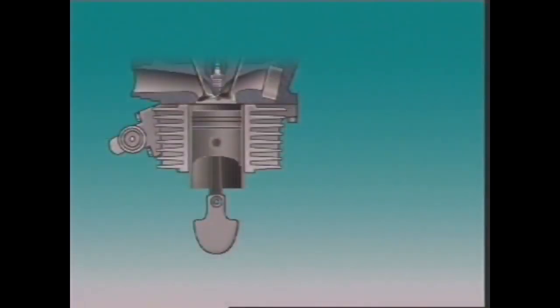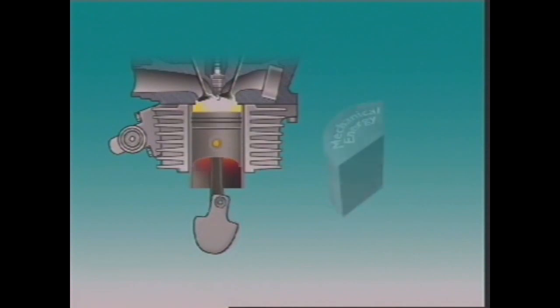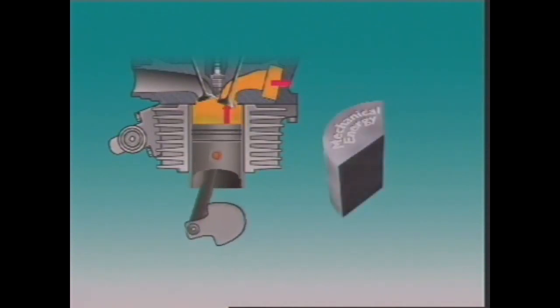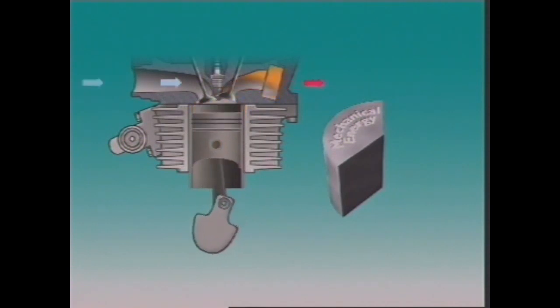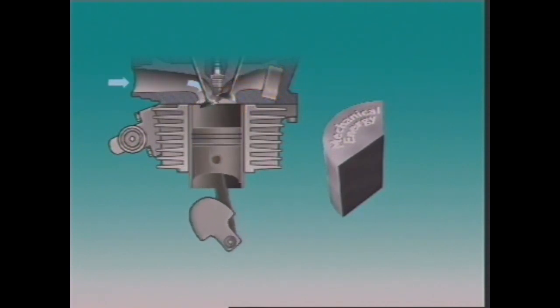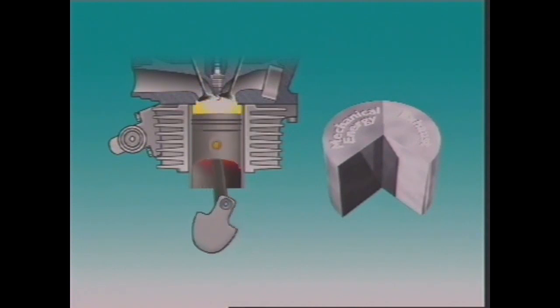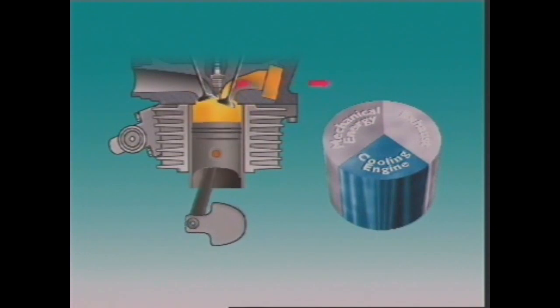This is certainly true in internal combustion engines, where only about a third of the heat generated is transformed into the mechanical energy that moves the piston and turns the crankshaft. Another third goes out the exhaust, wasted. The rest tries to spread round the engine.